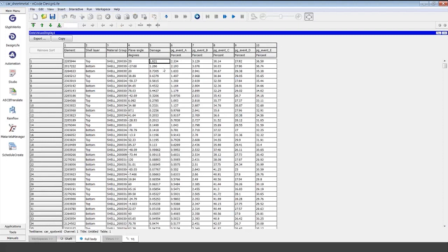And by the way, as you can probably guess, we have a fatigue problem on our hands here, because it says the highest fatigue damage is 1.6. In other words, we won't even be able to complete a full duty cycle, say 150,000 mile life, before failure. So we've got a pretty critical fatigue hotspot here. And if we do, we may then wonder, what's driving that fatigue? What fatigue cycling drives that fatigue damage problem?